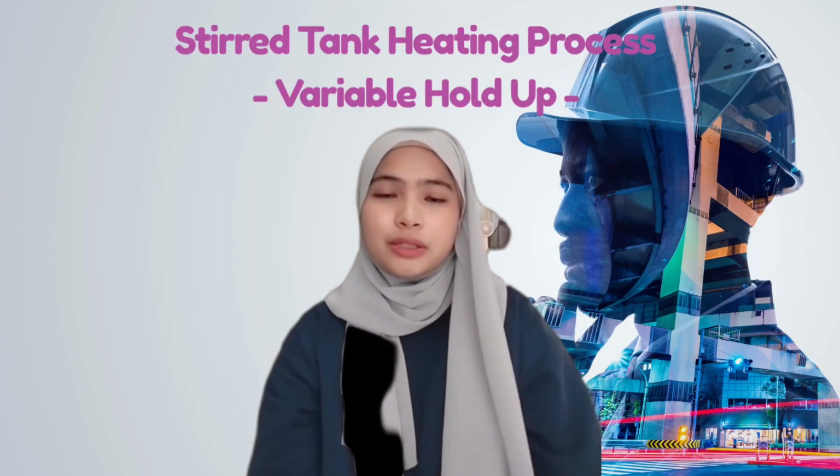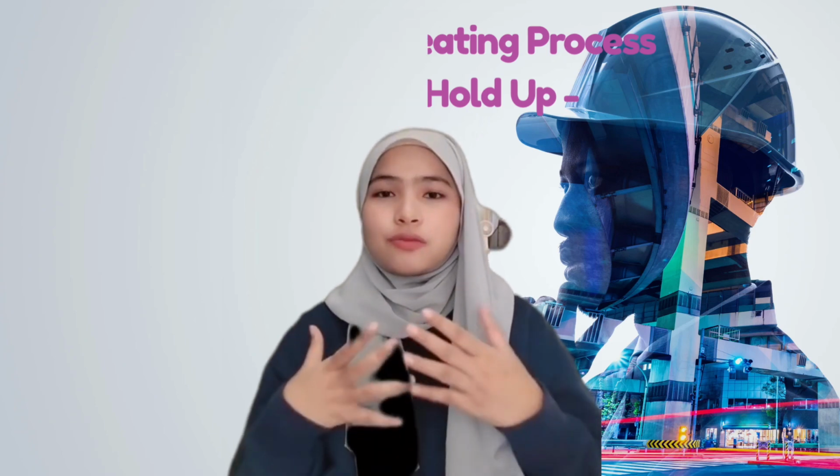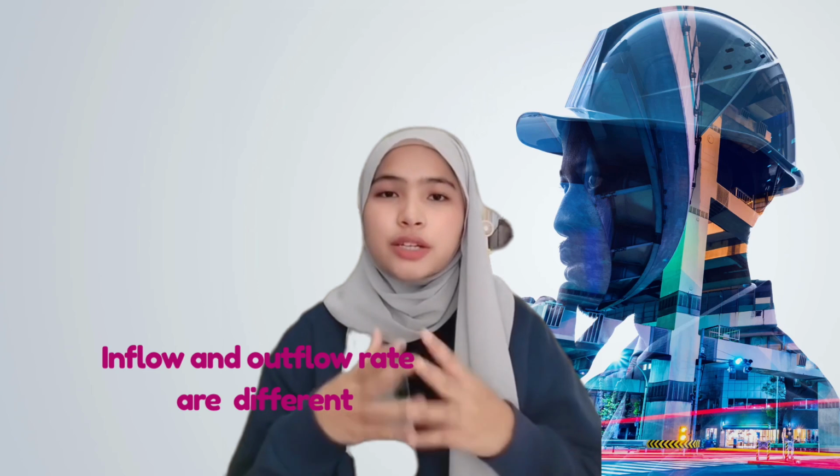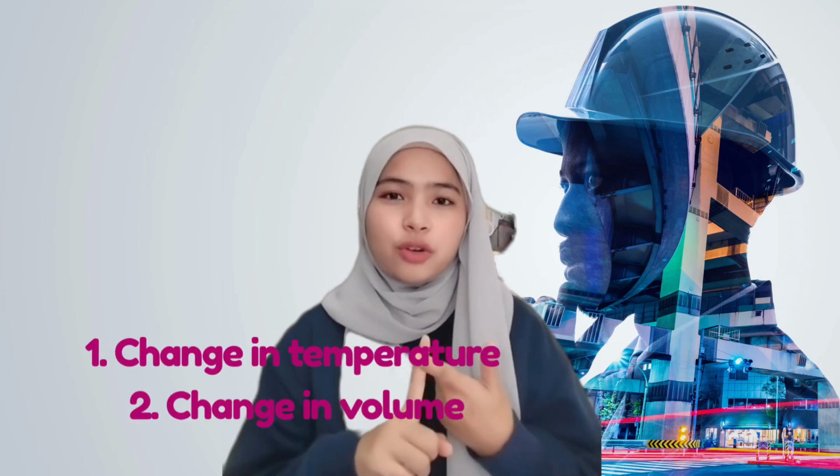Next, for the variable holdup, the volume inside the tank is not constant, meaning that the inflow and outflow rates are different. So, both temperature and liquid volume can change over time. Let's start with the same general energy balance equation, but now when we differentiate the internal energy term, we must consider 2 parts, which are the change in temperature and the change in volume. And the mass balance relates the rate of change of volume to the difference between inflow and outflow.